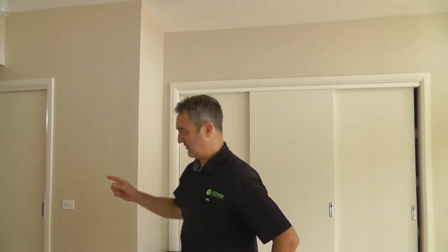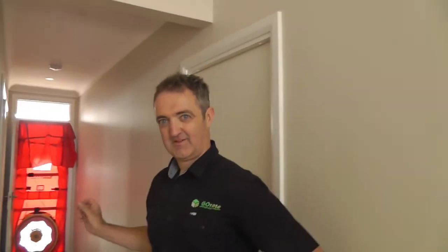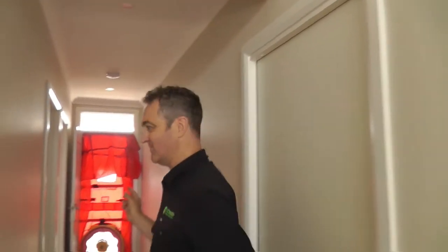Now follow me, we've got the blower door set up in the front door. What the blower door test does is basically test the air leakage of the house. This house was built probably 5 years ago. Our current standard is about 10 air changes per hour. So we'll have a look at the dial on this and just see how we're operating at 50 pascals.